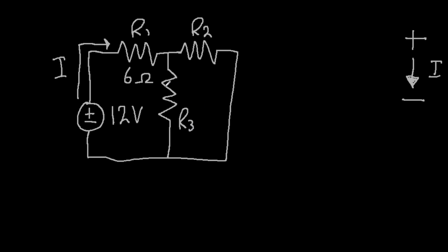How would you be able to tell that these resistors R2 and R3 are connected in parallel? Let's draw some positive and negative ends of these resistors to help you visualize it. One way to look at a parallel connection, as well as just having them next to each other like this, is to look at the way they connect. They connect at the same terminal here.